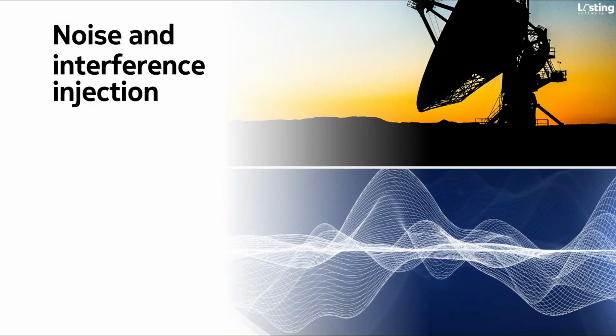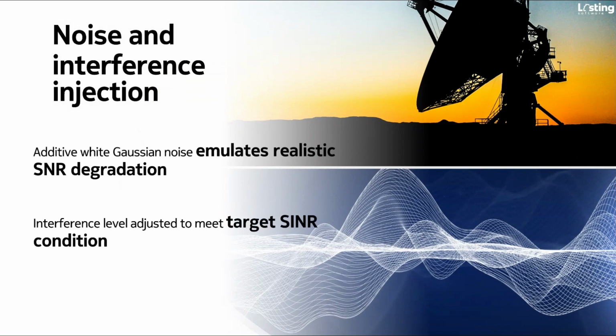CELEOS can degrade the signal using white Gaussian noise to emulate different SNR values. White Gaussian noise can be added digitally via live random number generation, while to simulate interference, we inject either a pre-recorded 5G signal or DVB-S2 signal. This can be done by using pre-recorded signals via SigMF.